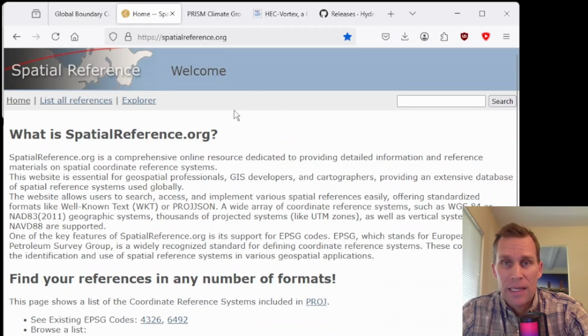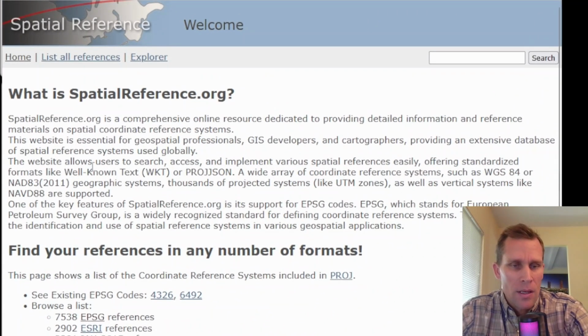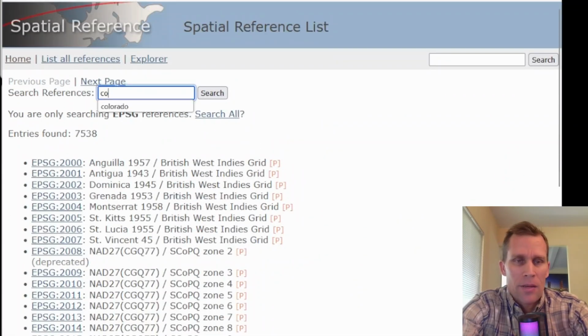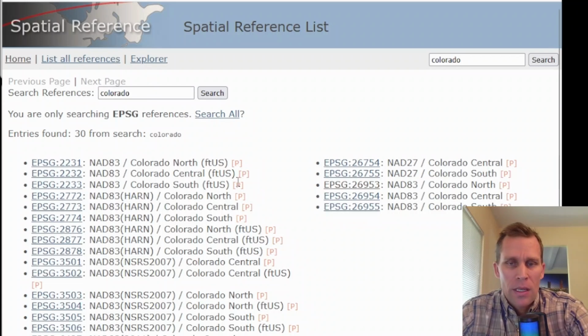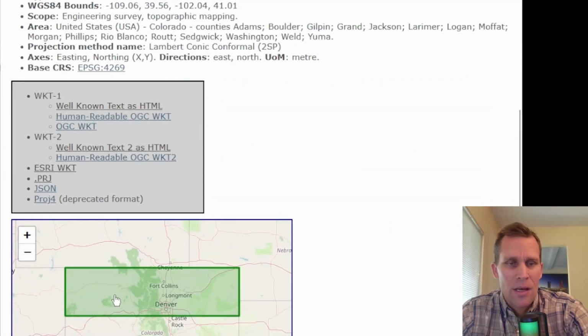I'm going to add a bunch of links to the description of this video. Spatialreference.com. I'm going to click on EPSG as the projection type, and then I'm going to be working in Northern Colorado. So I'll click on Colorado, and then Northern Colorado, I'm going to download this one right here, 26953, and we have some well-known texts, a map.